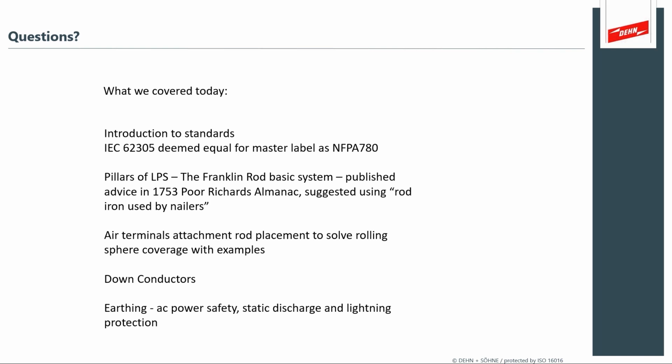Yeah. I think it's a matter of when you get started on the project. If you are involved with the project from the beginning, and aesthetic issues, I think it is actually preferred to get the down conductor within the concrete, bonded to the reinforcing as it heads all the way down to the ground. It also adds a bit of electromagnetic screening that we can receive from reinforced steelwork. But obviously, if we get pulled into a project once everything is already standing, you have no choice but to run a down conductor on the side of a structure.